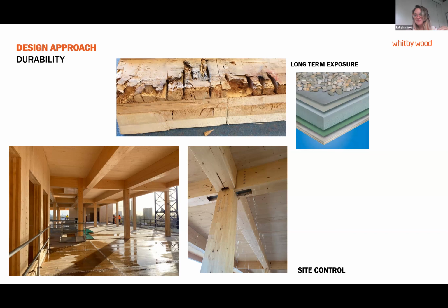Put some falls in, put some detection in. There are amazing detectors out there now you can put in very easily. Speak to the building management system, the BMS, and it can tell you if the moisture content's getting too high. The architect needs to think about how they're layering up the waterproofing. Where is the point of failure if it's going to happen? Are there two layers of protection? Is it embedded in the timber, or is it on top of the timber? Think about the routes the water can go and where it can drain away to. So all needs thinking about from the very start.